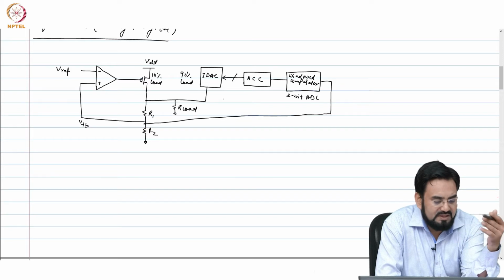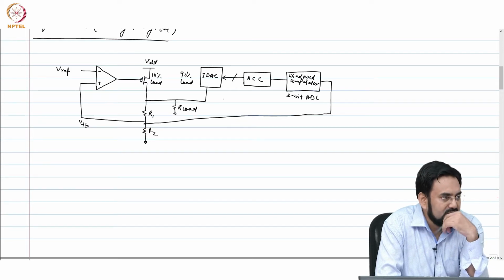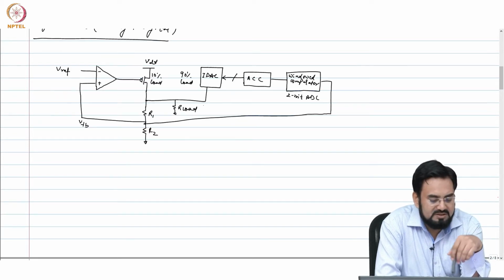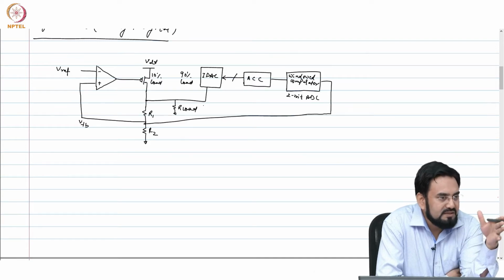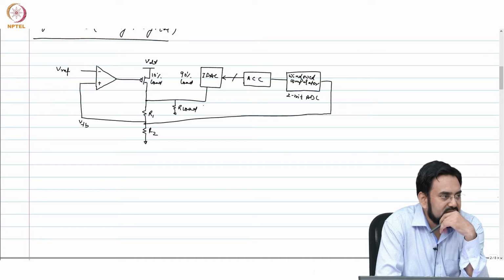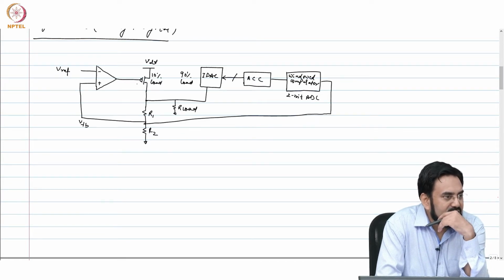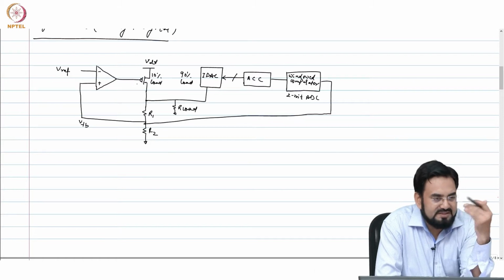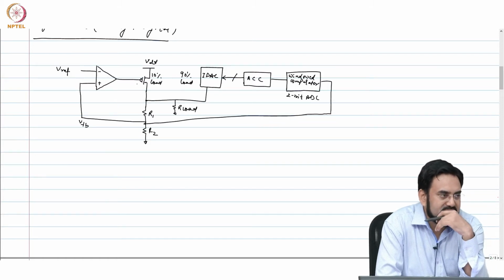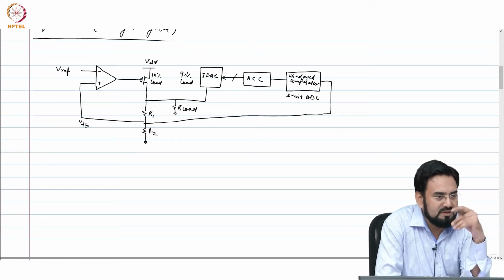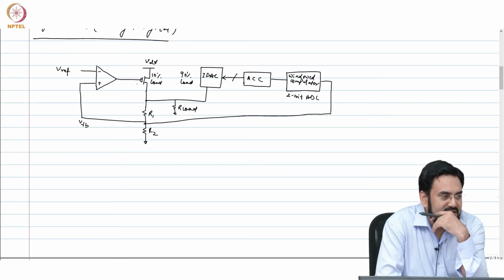So, it goes let us say 1.1 milliamp or so. So, depending on the resolution it will turn on that many IDACs which will carry 100 microamp of that extra current. So, this will remain at 1 milliamp, okay. So that's one way, and that threshold you can set it lower also, that doesn't matter as such. You can set at 500 microamp so that you don't go for full 1 milliamp, because you don't want to saturate that.